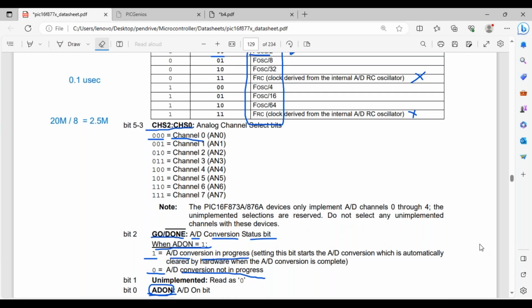How can we control the brightness of the LED? I think we did a classwork where we implemented an LED dimmer application. As I press the switch, I increase the duty cycle and accordingly the voltage delivered across the LED also increased. As I press switch 2, I decrease the duty cycle and the brightness of the LED decreases because I'm providing lesser voltage. And that has to happen in a very swift manner.